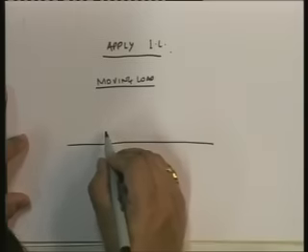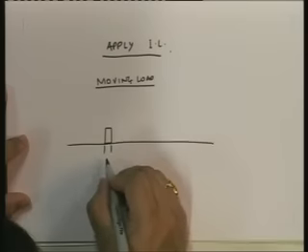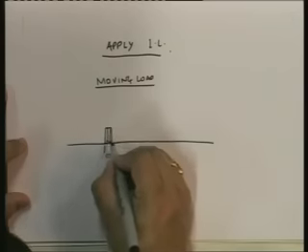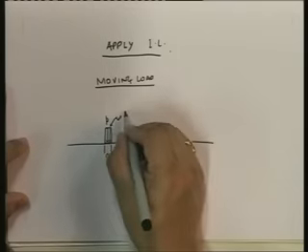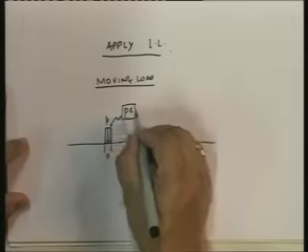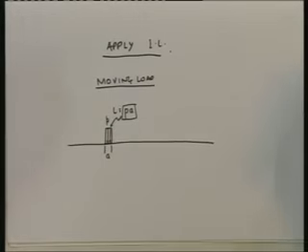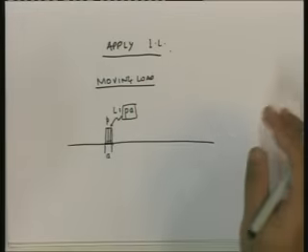One kind of moving load that we can have is something like this. Over some length A, we have a uniform load intensity p, so that the total load is p times A. When does this kind of thing happen? This happens when you have a truck or a car traveling over a bridge; there is an area over which the load is distributed.